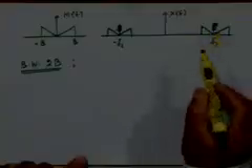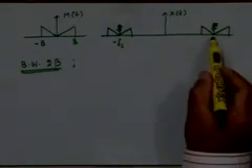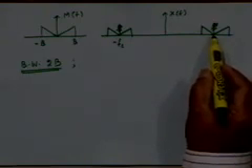But you can't say that there is a component at FC, right? You have to have some understanding of what a density function means and what impulses in the density function mean. When you have an impulse in the density function, that means there is a localized component at that frequency. There is some finite power or energy that we can talk about at that frequency. Otherwise, when you have a value of a density function which is not impulsive, if you ask how much power is carried at that frequency, the answer is 0, right? So you have to understand that issue.